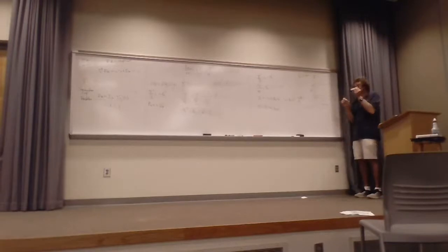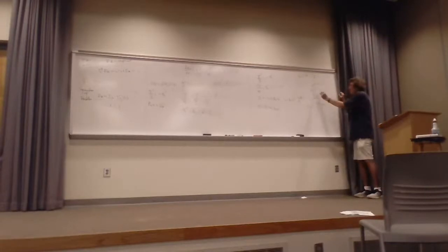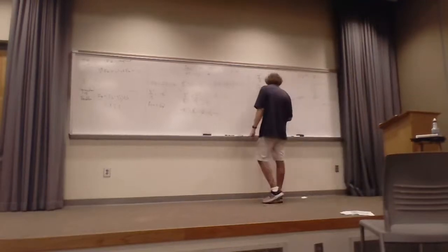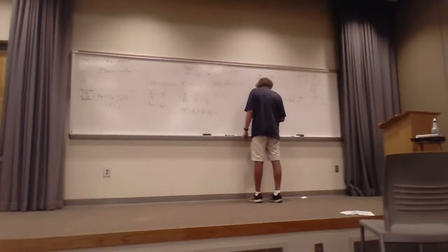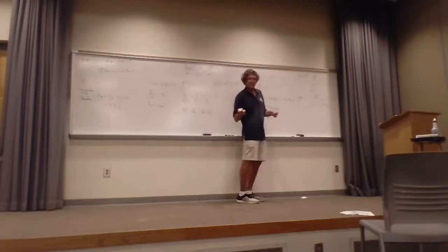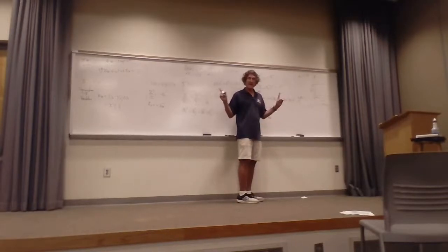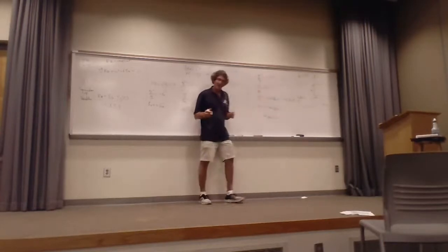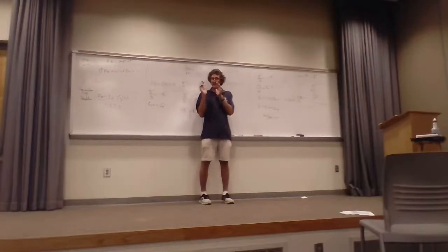Remember, I'm trying to use this marker to indicate E_z. It doesn't matter what y is, but in the center, at least you can see that as it hits this edge, it has to go to 0. So what do you know? That at that edge, the sine of beta x times, well, what's the length there? The horizontal dimension. Can you all read that? a, right? So beta x times a has to be 0. All right, what arguments of sine are 0? Well, when the argument of sine is 0, it's 0, right? What's the next 0? Pi, isn't it?